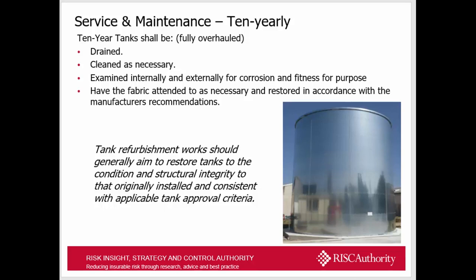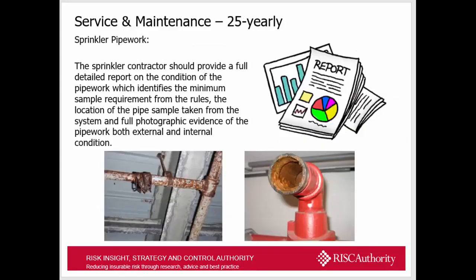And there's also a requirement there. Tank refurbishment works should generally aim to restore the tanks to the condition and structural integrity of that originally installed, and consistent with the applicable tank approval criteria. So for above ground storage tanks, when you do any refurbishment work to the tank, it should be restored to LPS 1276 standard, or as near to as possible.